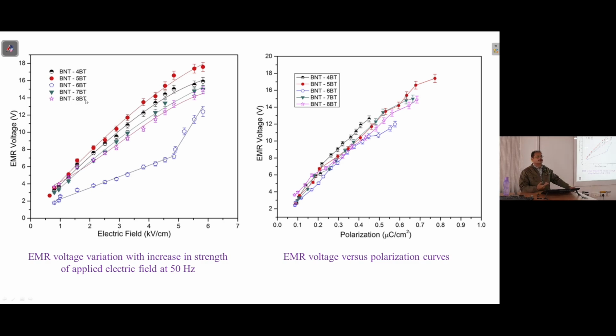If it is rhombohedral, then different orientations are possible, and the same way for the tetragonal. With each of these, there will be certain specific polarization directions. When you apply an external electric field and the material gets polarized, it happens along certain specific directions within the unit cell, but not in all directions. So each one of these has certain preferred polarization directions.